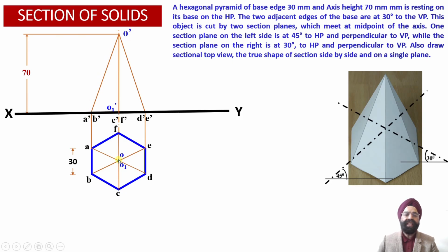Similarly, the slant edge OF is also lying on the back side, but again it has been covered by the slant edge OC in the front view projections over here. This way the dotted line projections corresponding to the slant edge O dash F dash will be covered or superimposed by the object line projections corresponding to the slant edge O dash C dash in the front view projection.